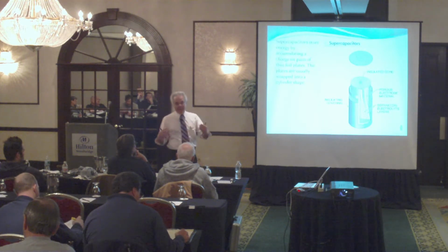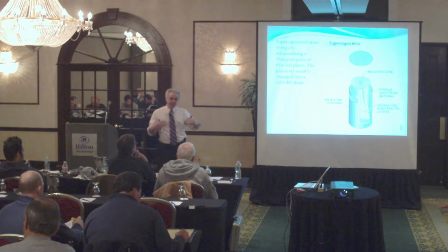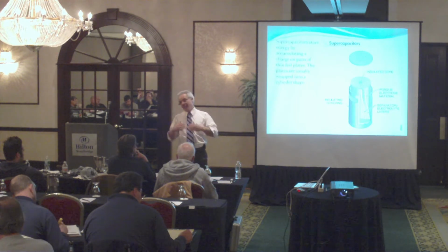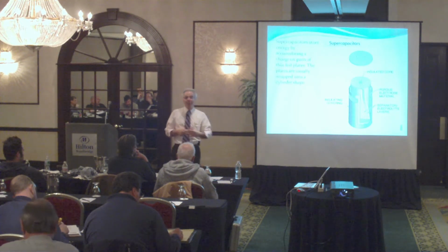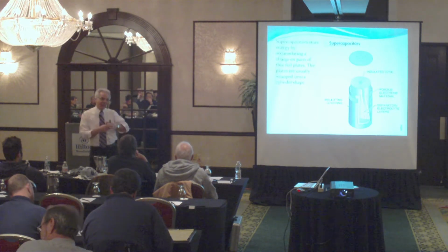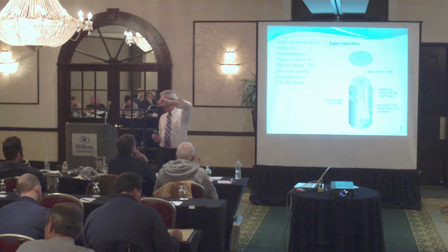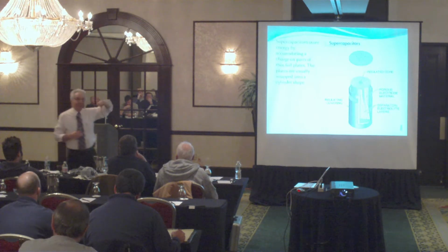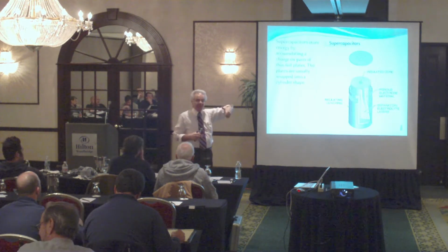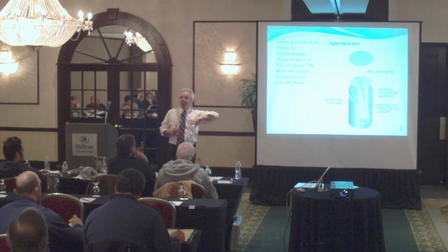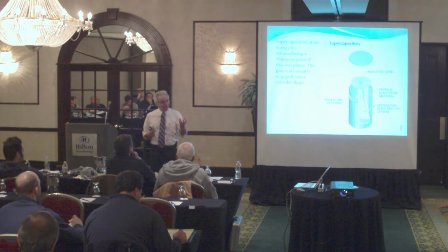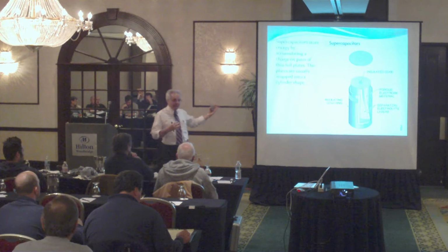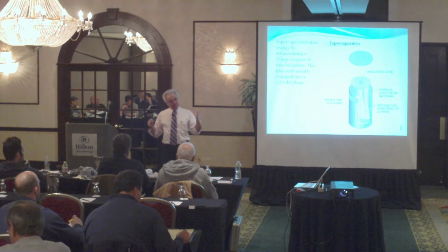The unfortunate thing about capacitors is that to store a lot of energy, you need huge capacitors. Capacitors are measured in farads. Most of the time you are familiar with microfarads, tiny little capacitors, for example the ones used in motors. You see the little bulky thing on top of the motor? That's a capacitor. Usually you use that for starting the motor and also improving the power factor. That is physically measured in microfarads, which is millionths of a farad.